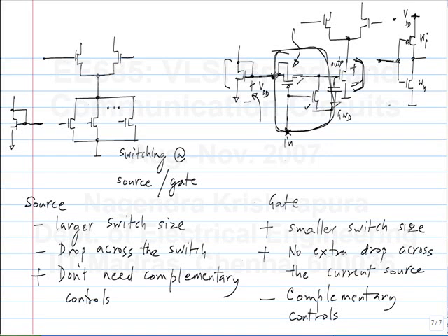Still, when you split up a single transistor into multiple transistors, the MOSFET width is the same, but you have to connect them with wires and so on. So the capacitance here will still be large because of all these wires that you have to route. So think of some ways in which you can vary the taps, but you don't have this extra overhead. You can try and vary it continuously. There are some problems with it. We can discuss it afterwards. It is sometimes done, but it's not very desirable.